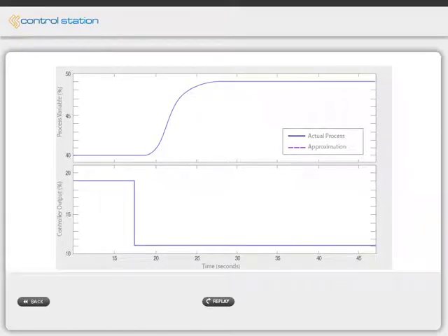Data from a proper bump test is rich in dynamic information that is characteristic of our controller output to measured process variable relationship. A first-order plus dead time model is a convenient way to quantify key aspects of this relationship. The plot on your screen shows an FOPDT model fit as computed by commercial software. We call this fit the base model, because we can visually see that the approximated model closely tracks the real measured process variable data.